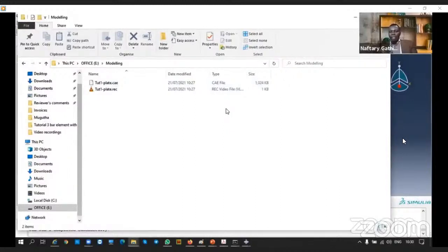Depending on the quantities that you have requested, you can request stress. And remember, this is 3D stress. So you can have the principal stress in all the directions, the shear stresses. You can have the von Mises stress, so many stresses requesting. And maybe you're not going to use them. You don't need them for your analysis. Then you might have a very big report.